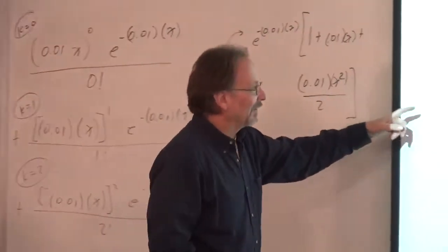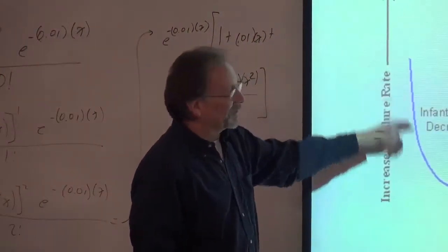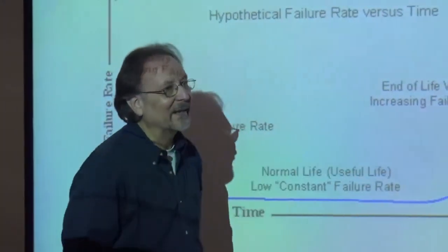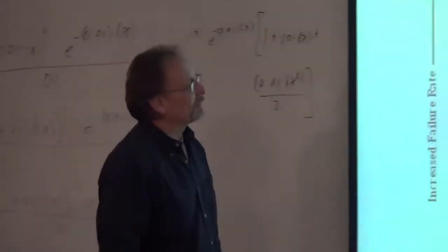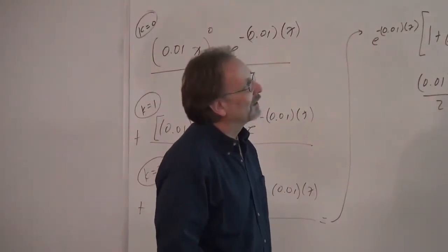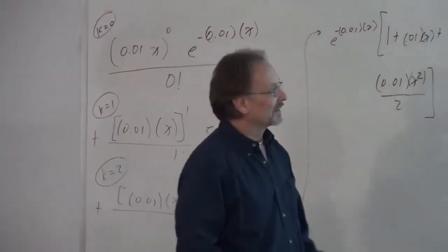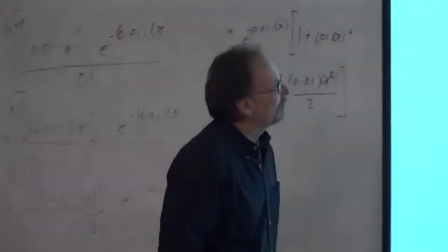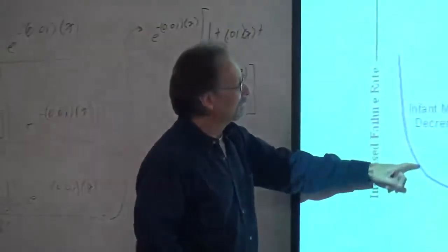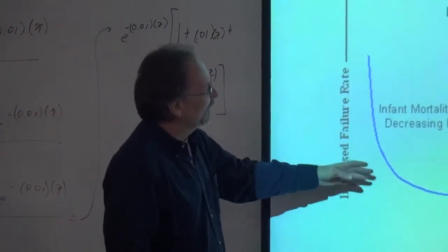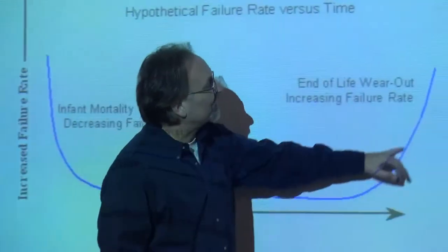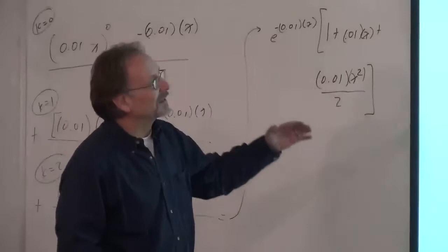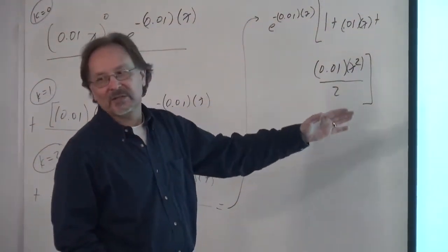If an electronic component is going to fail, it fails at the beginning, or it fails when it's getting closer to its expected failure, its mean time to failure. Right? And this is called a bathtub curve. You can model that largely using the Weibull distribution, because this is early failure and this is late failure, by adjusting the alpha. You can also use exponential here, because that's a variant of the Weibull. You can use uniform in here, and possibly quadratic out here. But Weibull is useful in that you can apply it to the entire life of an organism, component, whatever.